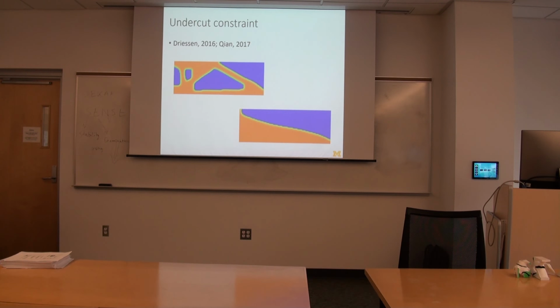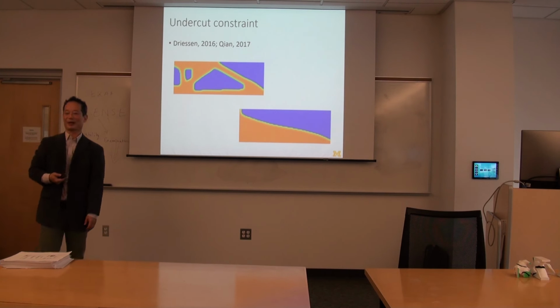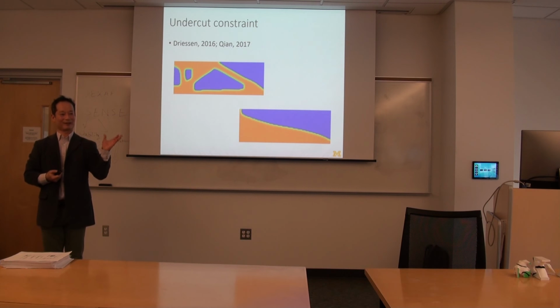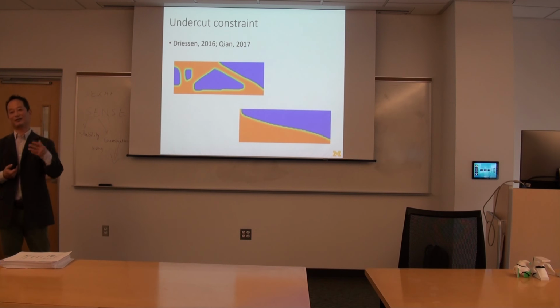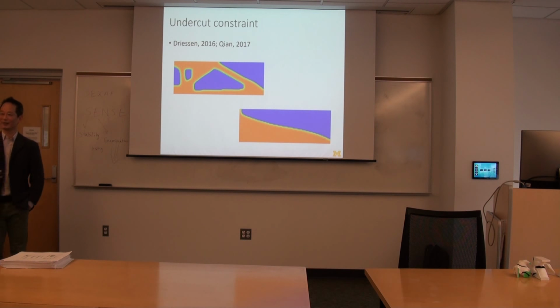And so we tried to figure that out. Well, but then somebody did it. Okay, so we didn't really bother to reinvent the wheel, so we use this method people created, which tries to measure the undercut as the gradient of a density field around a portion where the density is very low versus where density is very high. So you just look at the gradient, and you can approximate undercut values in a certain direction by taking a dot product with the gradient in that direction.